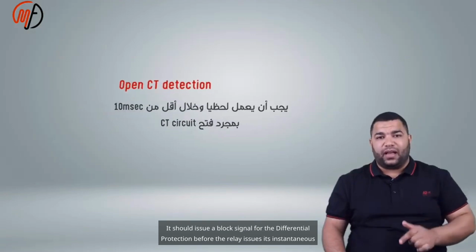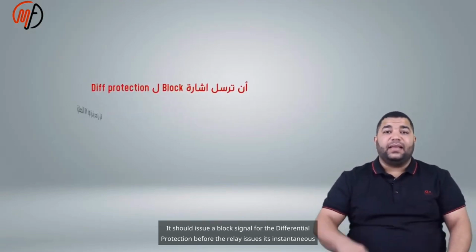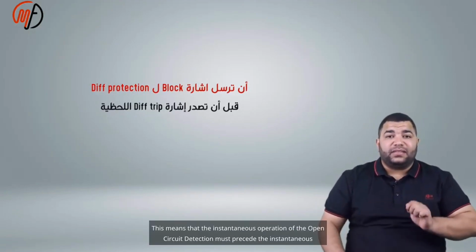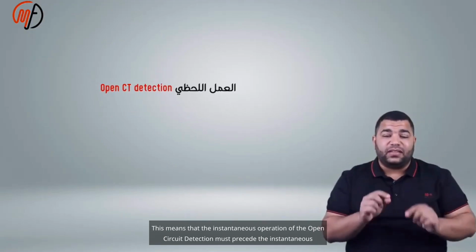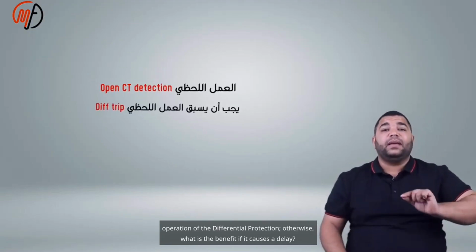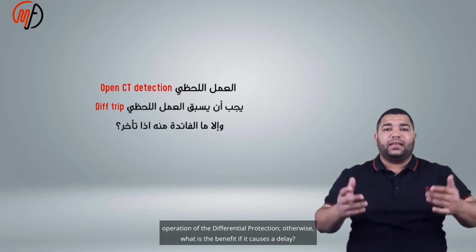It should issue a block signal for the differential protection before the relay issues its instantaneous differential trip. This means that the instantaneous operation of the open circuit detection must precede the instantaneous operation of the differential protection. Otherwise, what is the benefit if it causes a delay?